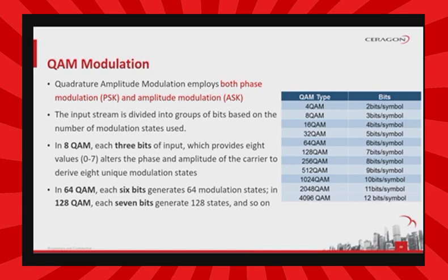the original modulating information. Higher quadrature amplitude modulation is normally easier to generate and demodulate than higher PSK, because QAM can simply be formed from two orthogonally distanced amplitude shifted signals, whereas in higher orders of PSK, one needs better angle detection that is harder to obtain.